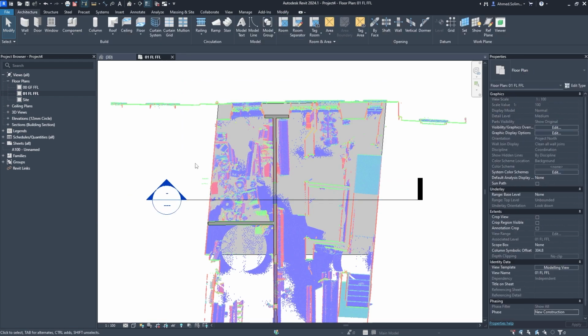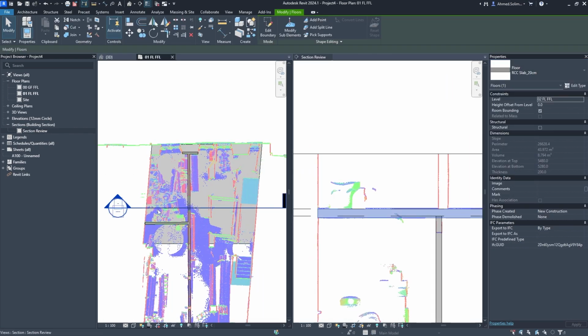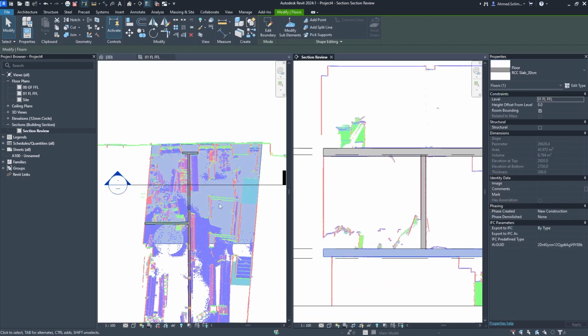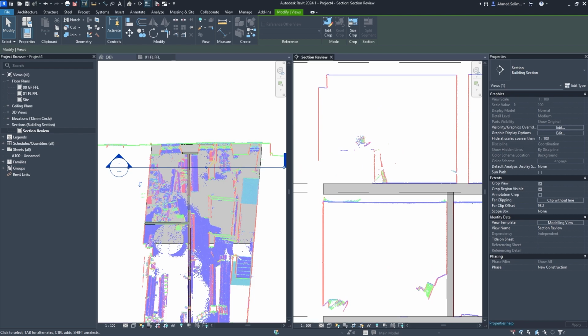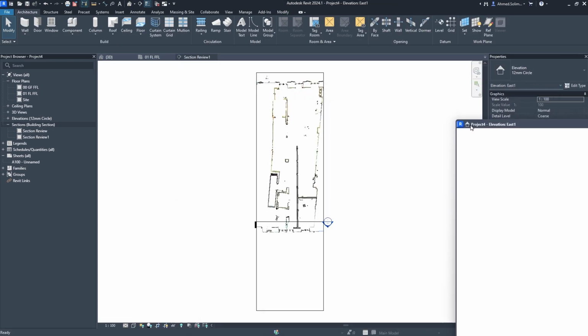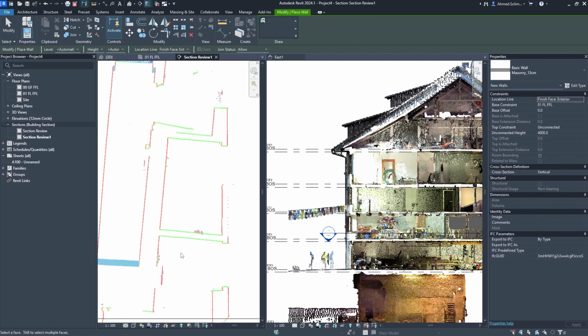Another helpful idea is creating a section with a short range. This can be used vertically to check sections or flip 90 degrees horizontally to check plans. Open one tab to move the section line throughout the model and use that section's view in a separate tab to compare your model to the point cloud as you model. This allows you to get a closer, more dynamic look at the item you are modeling without the distraction of the background.